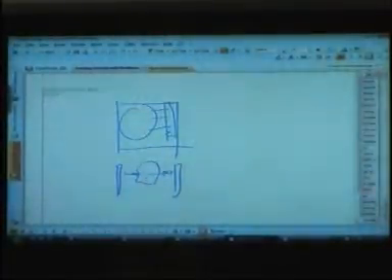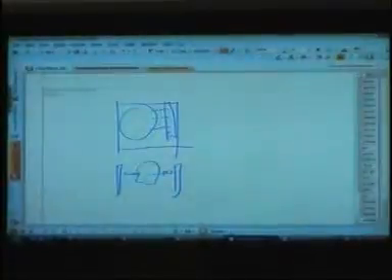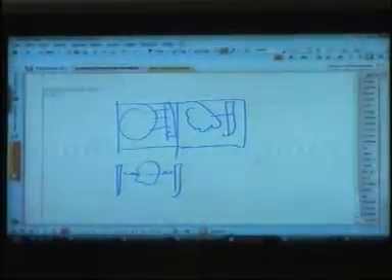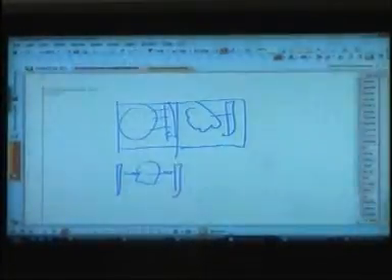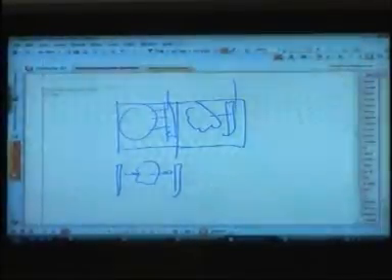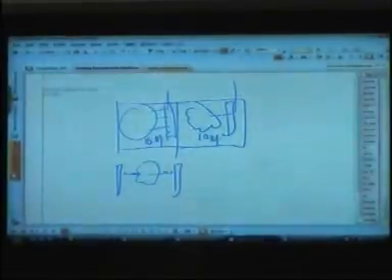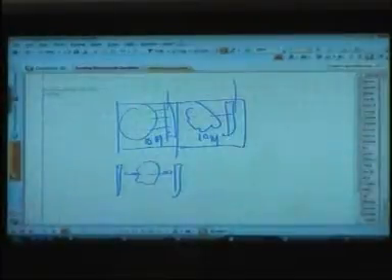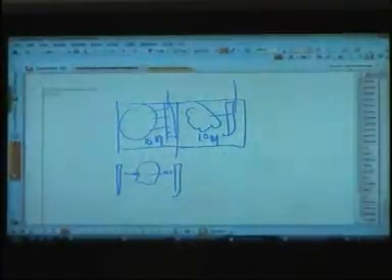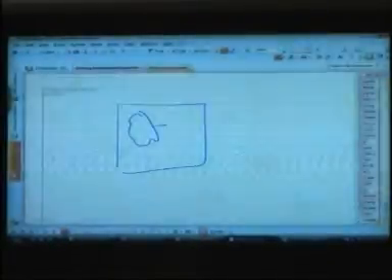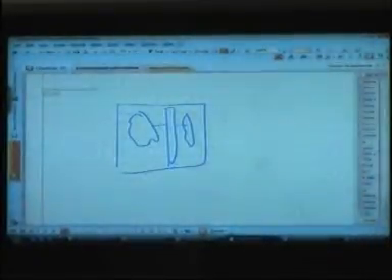So you partition a design in a way that outputs are always registered, so that once you put another module done by another engineer, or even by the same engineer, and now you synthesize, the timings are from register to register. Okay, if registers are at the output and this block is working at 10 megahertz and this block is working at 10 megahertz, then it is guaranteed that the 2 blocks together will also work at 10 megahertz. Why? Because we can see the timing from register to register. There may be other registers inside the module, but if this is not the case, and a person has designed something where there is logic, a number of registers, and then again combinational logic, and he comes and tells you, oh, my design is working at 40 megahertz.